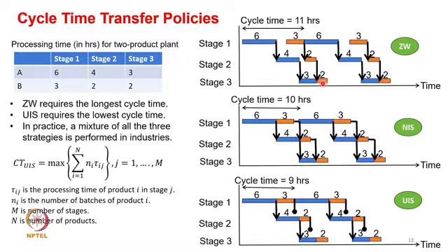Your third stage is only available after 3 hours of A. So, let us solve this backwards. These 2 hours we just keep as they are. Since there is no waiting time, immediately before stage 2 of B is activated, again for 2 hours, you can just move backwards and consider 3 hours of stage 1 for B. So, this is an AB and AB kind of structure. Now you can see that in this case, the cycle time would be 6 plus 3 plus 2, which is 11 hours.